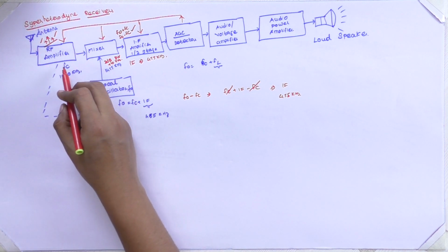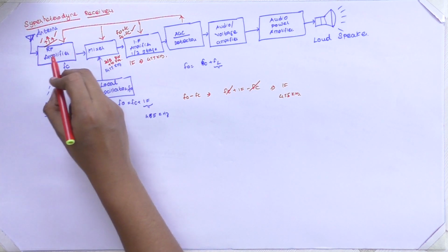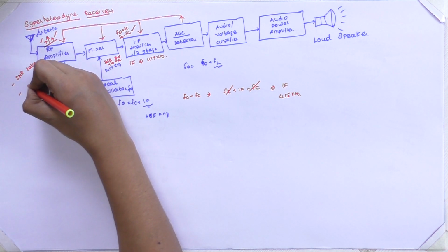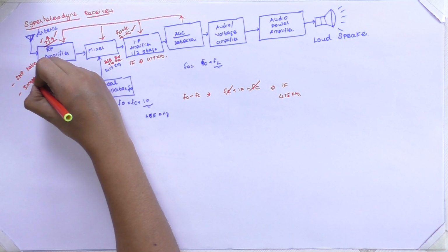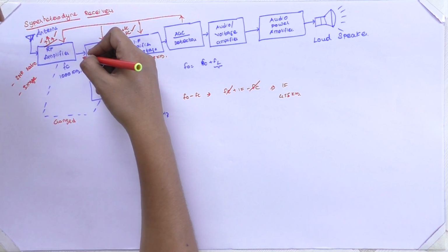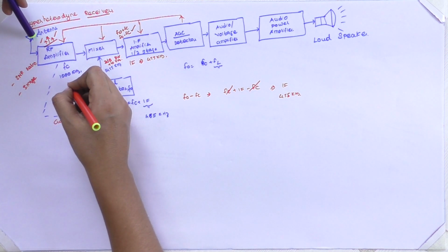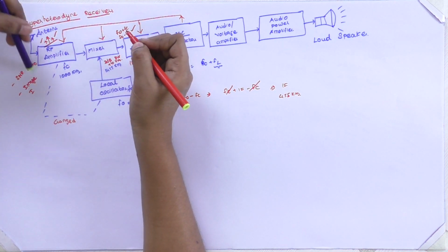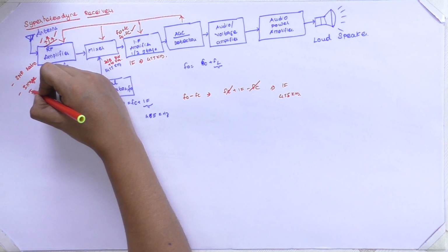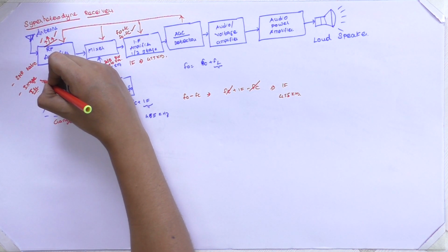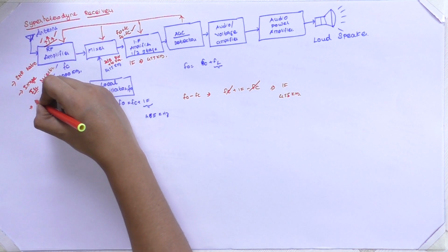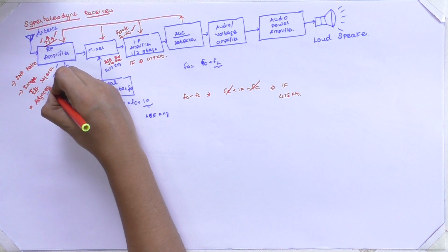The functions of the RF amplifier are to ensure the overall signal to noise ratio and also to give good image rejection, because a high frequency component may also get accommodated or a low frequency component may also get affected. We have to tune to the particular frequency. Therefore, our RF amplifier section must ensure high image rejection, frequency rejection, and it also ensures adjacent channel selectivity.